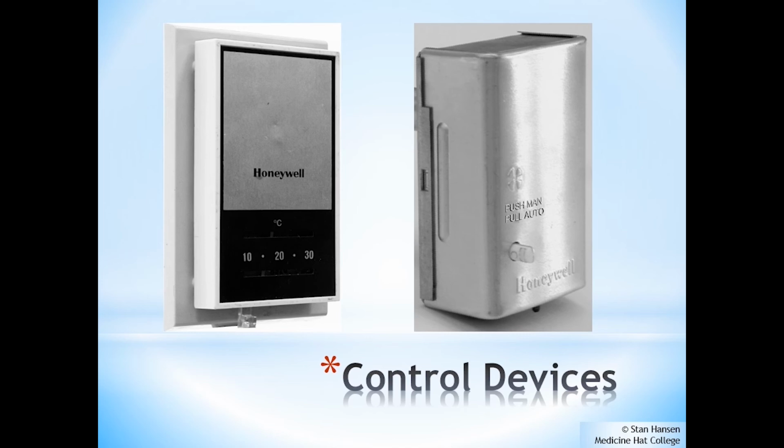The third control device is called the fan control switch. It operates the furnace blower to move the warm air around. It allows the air inside the plenum to warm up before it starts up the fan, and it shuts off the fan when the plenum has cooled to a safe level. It also includes a manual override that allows the fan to be run longer, which is good for temperature balancing inside the house. For example, we can take the cooler air from our basement and mix it with the warmer air inside the upper floors, and that will reduce our cooling costs inside the summer.